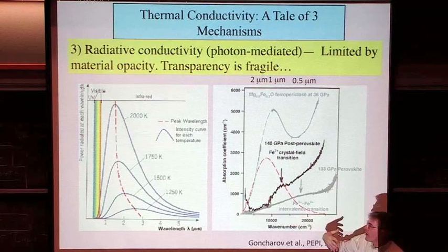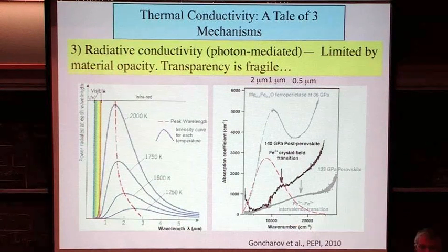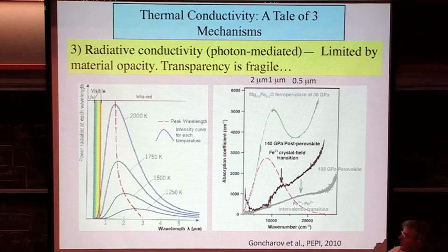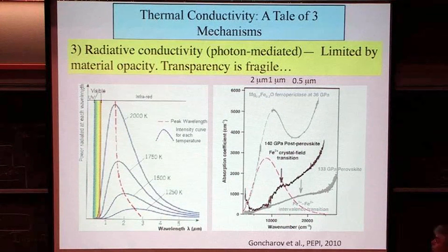Because photons are emitted thermally all the time, but if they immediately get reabsorbed in the material, you haven't moved any heat at all. You generate a photon, it radiates, gets reabsorbed, re-radiates in a perfectly spherical way, and then gets picked up, and you haven't moved heat at all. So if this number is even in the tens, you wind up getting zero radiative conductivity, or extremely little.